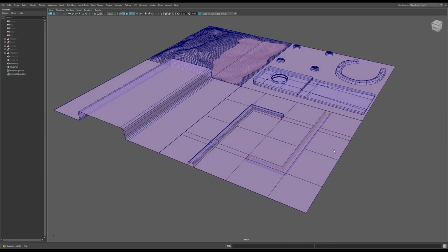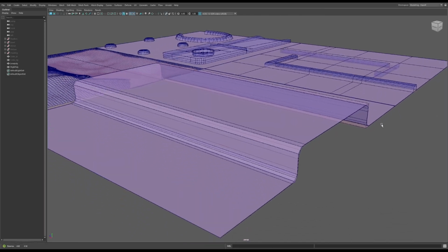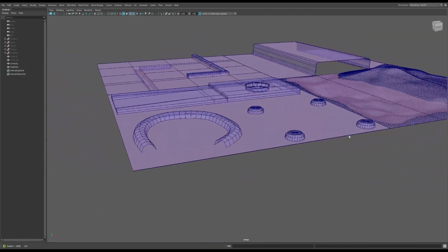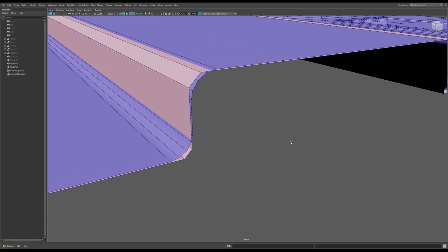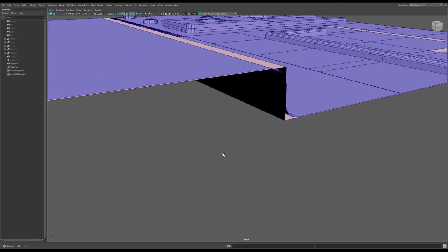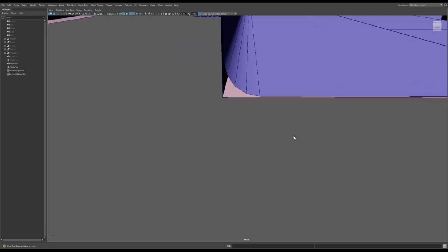Before you start exporting high and low poly, make sure they align and have the same pivot point. I also want to mention, bevels can be tricky. If the bake looks weird, bevel the low poly once, with one segment.